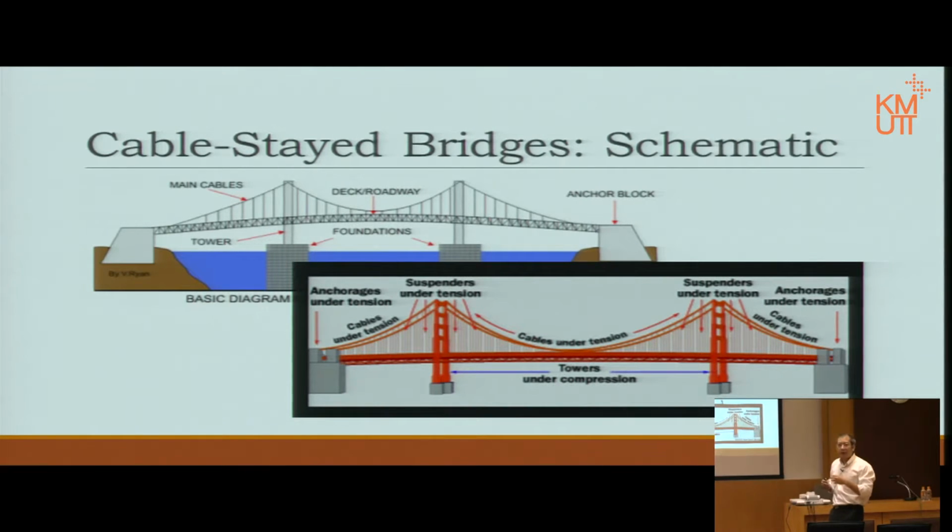So basically, rather than having only the sideways load transfer from the load weight to the foundation, some part will go up, some part will still go sideways, and some part goes up and then down to the anchorage, where it is pulled up by the anchorage. That's the way we set up the system of load transfer. Now, this is a complex system. So to understand this and to see the picture, we will look at the cable in a series of complexities, from a simplified version to the complex version.